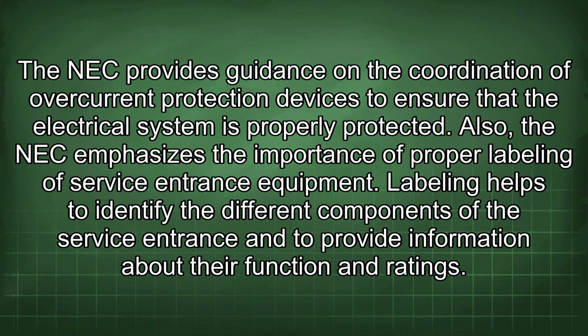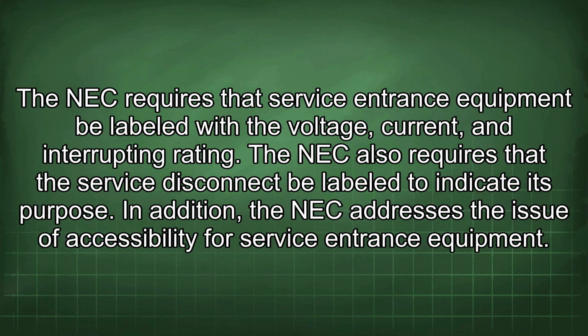Also, the NEC emphasizes the importance of proper labeling of service entrance equipment. Labeling helps to identify the different components of the service entrance and to provide information about their function and ratings. The NEC requires that service entrance equipment be labeled with the voltage, current, and interrupting rating. The NEC also requires that the service disconnect be labeled to indicate its purpose.